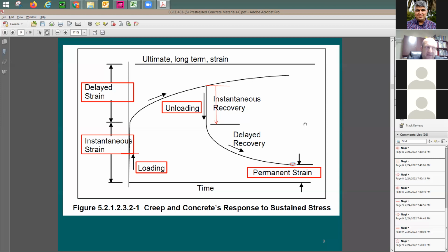The load stayed there. It's not a dynamic load by any means. This loading and unloading thing, because you keep it, let's say, for 2-3 days, you cannot call this dynamic. With dynamic force, you're going to have change in the force direction and magnitude, maybe in a fraction of a second, like in earthquakes. And with different performance. Yes.